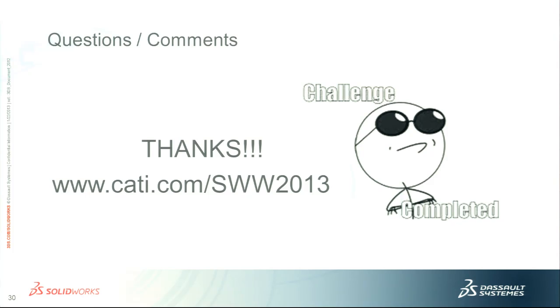Well, when you're using Workgroup, they have their own structure that they create that's based on a project, is what they call it inside the software. So whenever you check something in to Workgroup, it's going to grab that file and add it to the vault. And that's going to be a location somewhere on a server, more than likely, depending on how you have it set up. So if you want to duplicate that existing structure, when you check those files in for the first time, you have the option to maintain that same structure or have a brand new structure. So if you have a current structure that you want to copy, you would have that set up inside Workgroup in order for when you check them in and check them out that they get added appropriately.